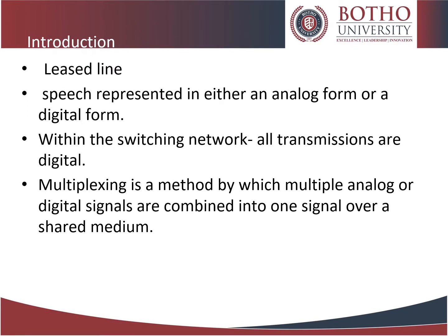By using a leased line, it is possible to arrange for a channel to be set up permanently between two subscribers. The speech relating to a call that is transmitted over the access line is represented in either an analog form or a digital form. Multiplexing technique is applied to share a scarce resource. With multiplexing, several telephone calls may be carried using one wire.